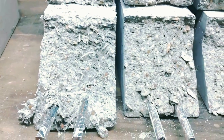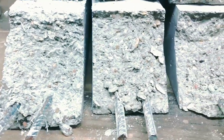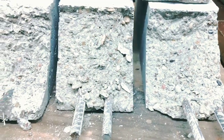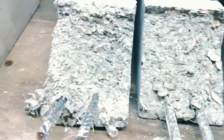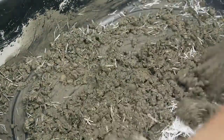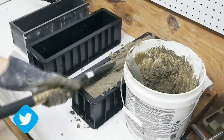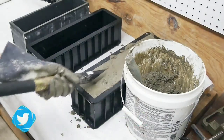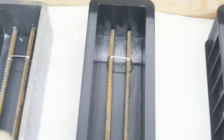Once the cause is identified, repairs can start, and one excellent method of repair is to remove all drummy and flaking concrete, remove all rust from the reinforcing steel, apply anti-corrosives to the steel, and then apply a fresh render so that the original look of the concrete is restored. Waterproofing can also be applied as necessary. By doing this, you can repair the areas of concrete that are damaged rather than having to replace the whole wall.